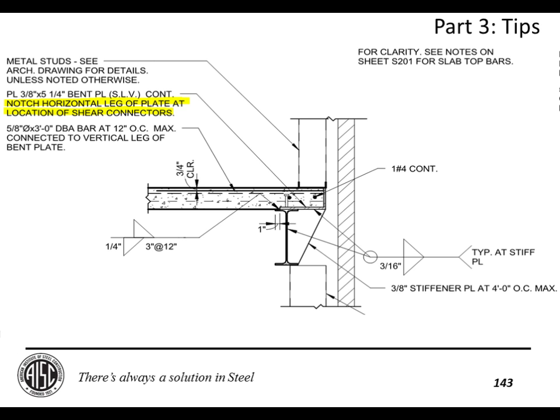One thing you don't want to do is require somebody to notch the horizontal leg of the plate at the location of the shear connectors. These are not my drawings. I apologize if they are yours.